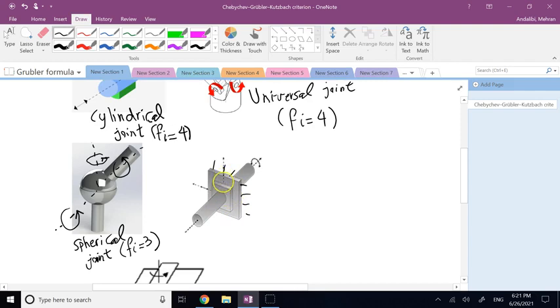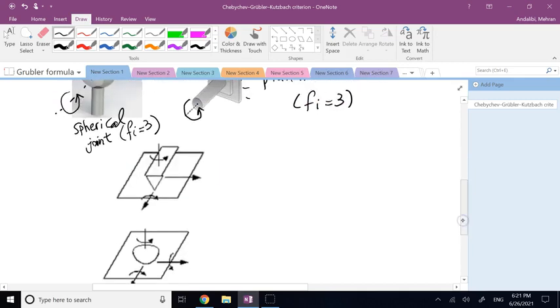So all it can do is one translation along this axis, the other perpendicular to that, and then a rotation on the axis perpendicular to the plane. So this planar constraint also leaves you with 3 degrees of freedom and takes away 3 out of 6. Then we have edge on surface contact.